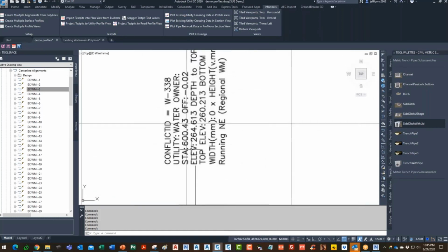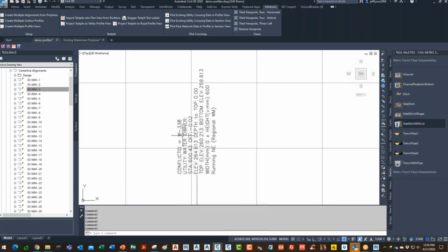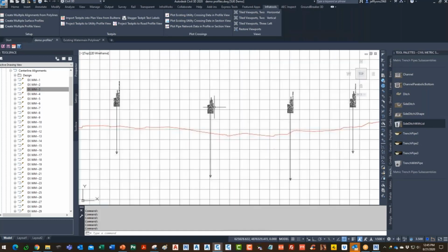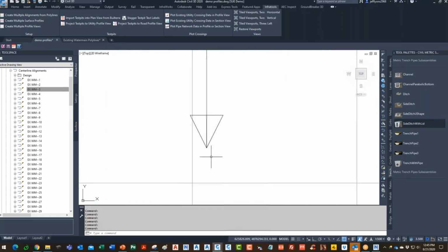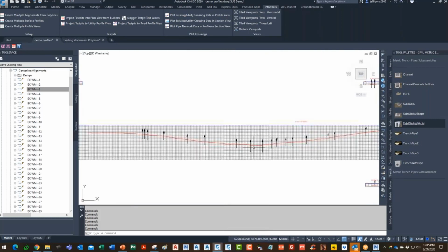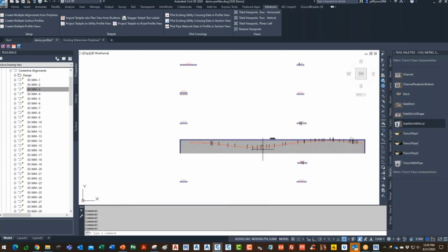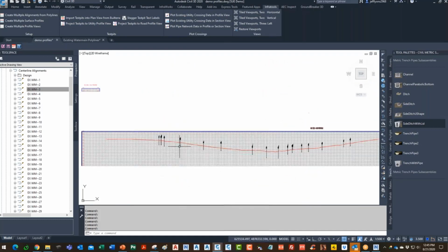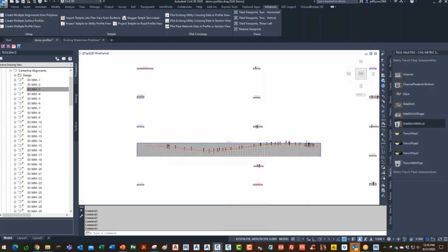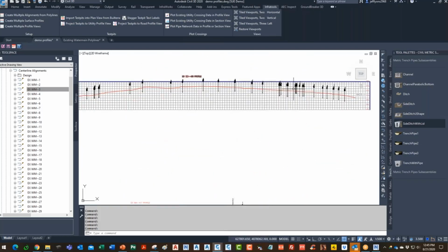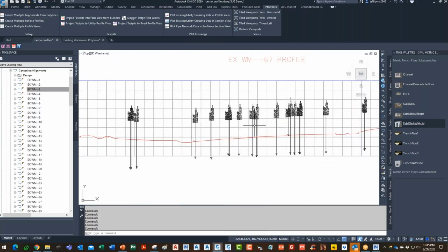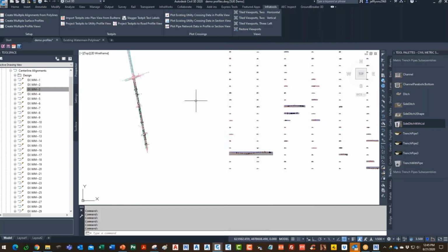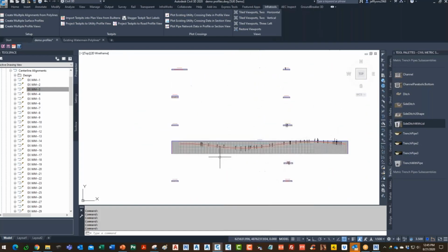This is mtext. I've customized that a little bit, but it grabs it right from the block, projects it, and then puts a little point right where the top of that utility is going to be. So within a few minutes, it's 12:45. You've just witnessed about 6 minutes worth of work to do 4 kilometers worth of data. So we've got this projection happening for the water main data. So this technically could be the water main model right here.